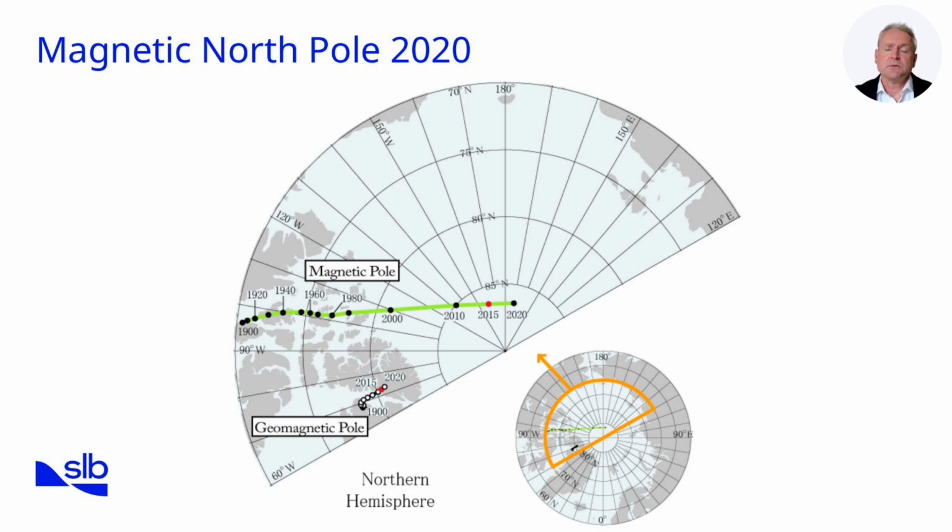The lesson is simple: never assume magnetic north is constant. Always consult the most up-to-date geomagnetic models, which provide declination corrections for your area. Modern survey software and service providers incorporate these models automatically, but as an engineer or geoscientist, you must understand the principle. Knowing that magnetic north is variable ensures you take the necessary steps to align your data with the fixed reference of true north.